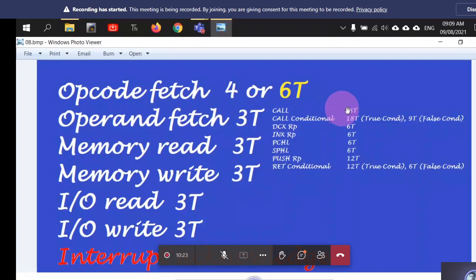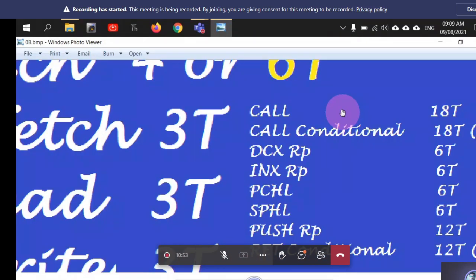But the point here was to demonstrate another category of call instructions, called conditional call statements. The plain call is simply a call statement: you write call, and after that there will be some address. However, there is another kind of call statement where you call a subroutine only when a certain condition inside the microprocessor is satisfied. For example, if the zero flag is set, then you want to call some subroutine. For that you have a statement called CZ, followed by an address.